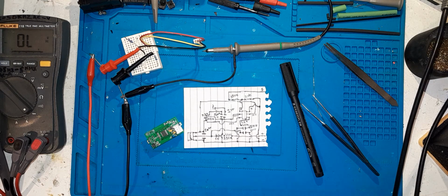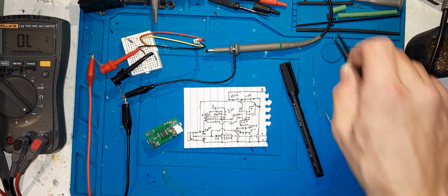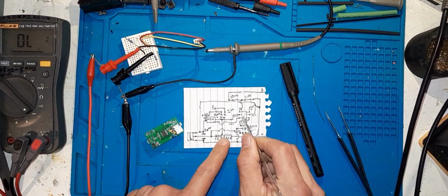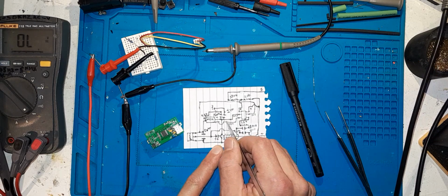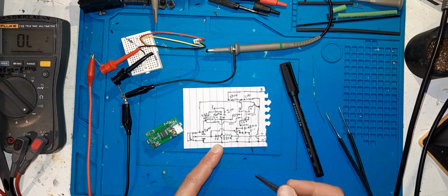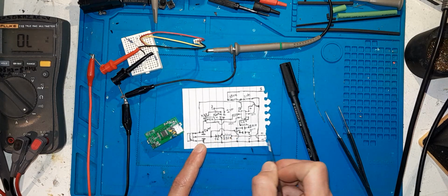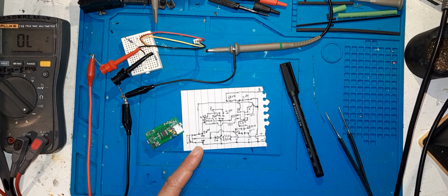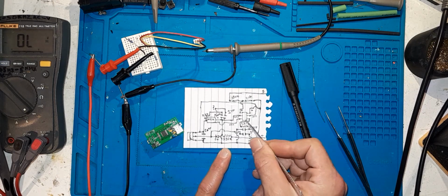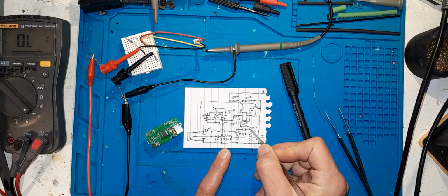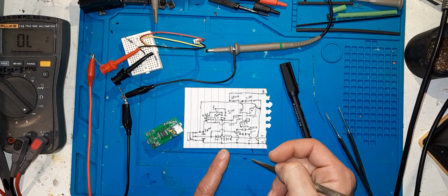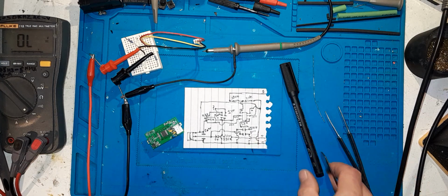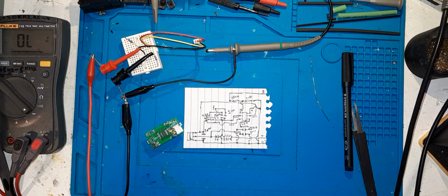So what that basically means is this device that I thought was an op amp is spitting out some sort of bidirectional data into the microcontroller, obviously referenced to ground. So that's not an op amp. I was right when I saw the snubber on one pin going to ground and the way it was set up. I was starting to doubt it being an op amp, so it's obviously not an op amp.